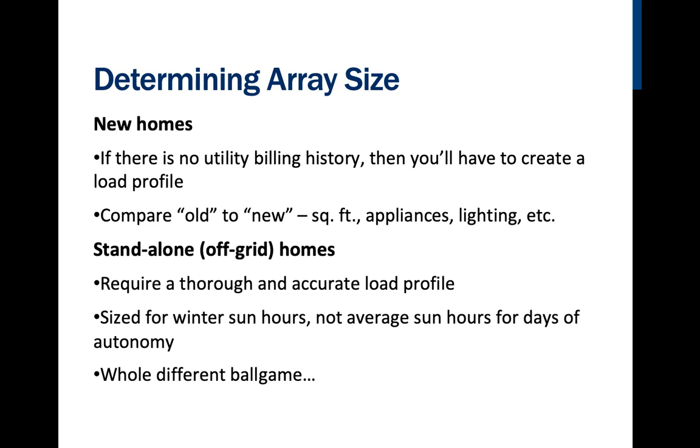autonomy without resource. We're assuming that at some time during the year we aren't going to have enough solar resources to charge our batteries. So this battery pack is going to be grossly oversized for most of the year and get us to squeak by through the good times, through the bad times.